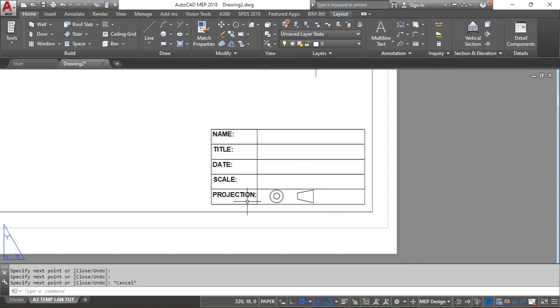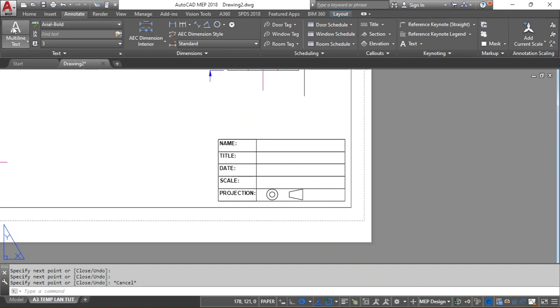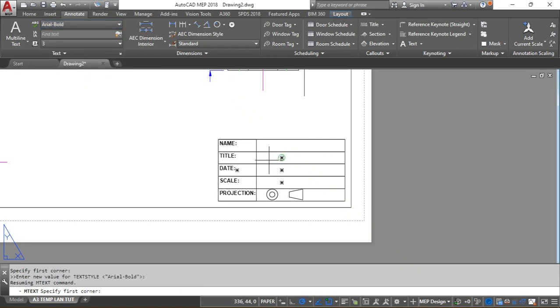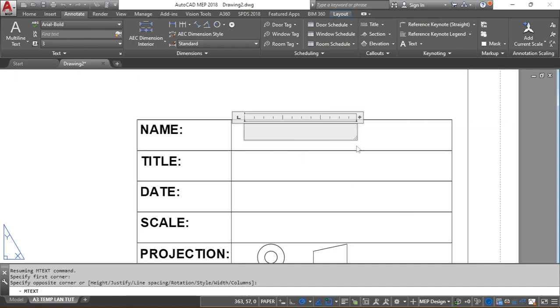Now that means first angle, orthographic projection, the scale is 1:1, and we can put a name. Maybe we can change this to that ghost something. So draw out a name, text area, and you can put the name.